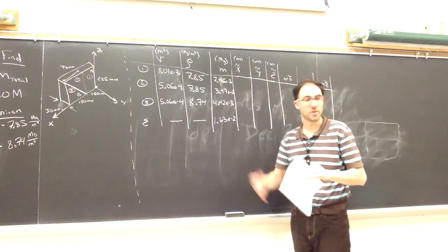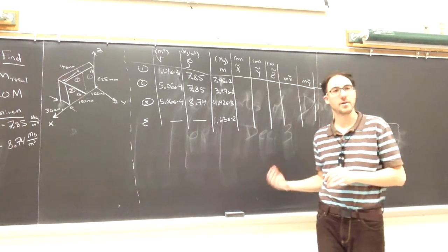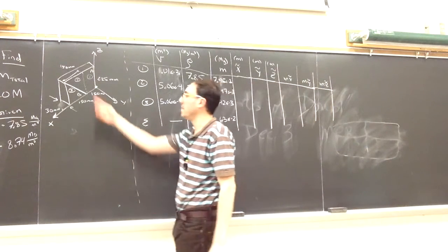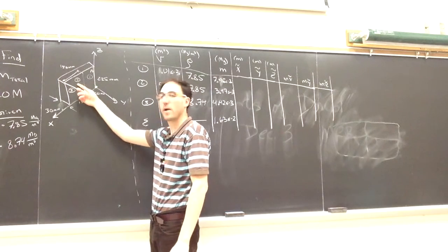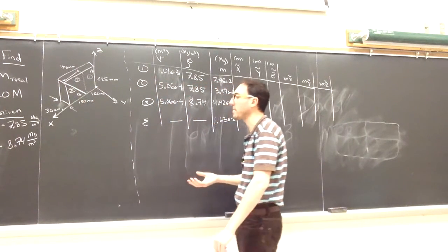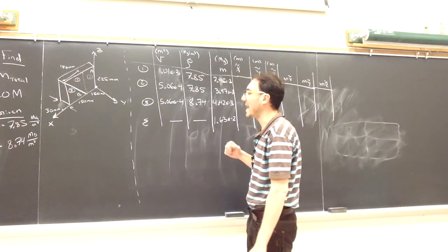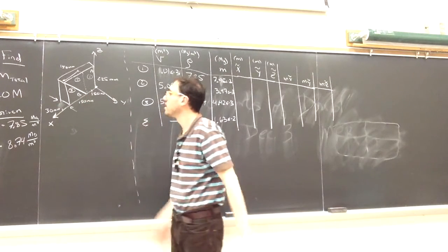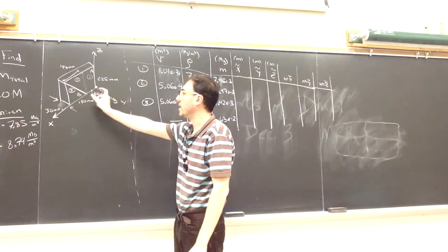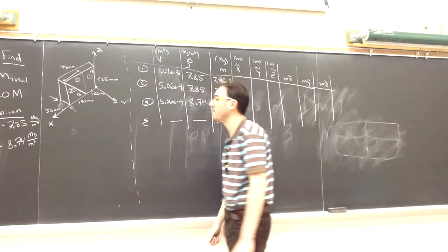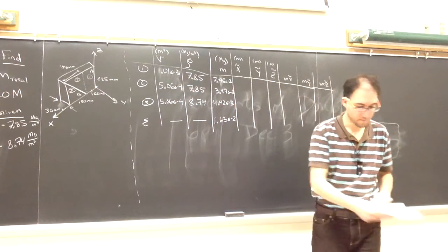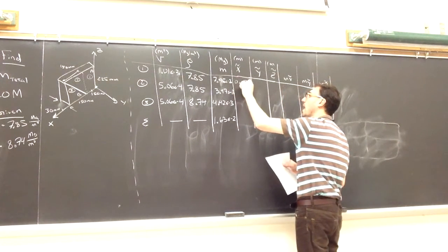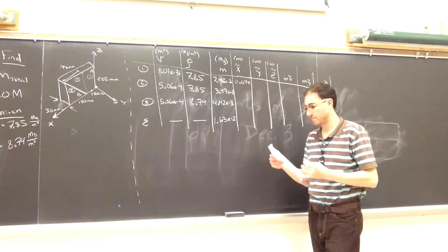Now it's going to look familiar to what we saw before, but we have to find x tilde, y tilde, and z tilde for each of these shapes. The same rules basically apply for a rectangular solid or the triangular solid that we saw for the 2D shape. So for shape number 1, for x tilde, measuring from the origin, we have to go by half of its base. It's 150 millimeters total, so half of that will be 75 millimeters in the positive x direction. So for shape number 1, I get 0.075 meters.